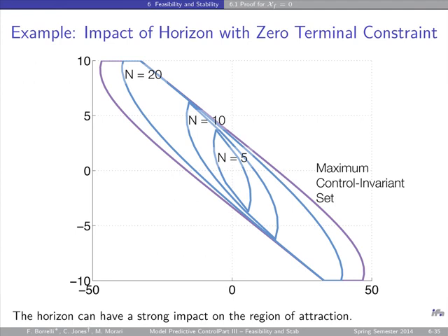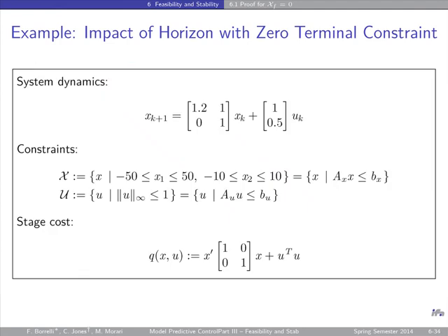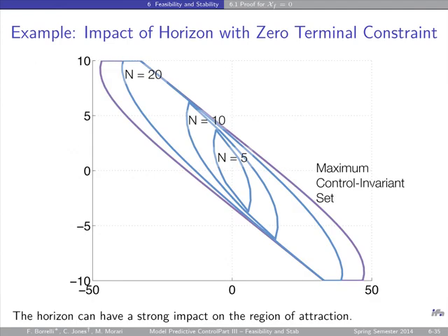how the initial feasible set changes as a function of the horizon. Okay, so the designer here has used the project I just showed, and set up an MPC with xN equals 0. And you see the blue sets here are actually the calligraphic X0, which are equal to O infinity, because of the proof that we have just given. For xN equals 0, you always have persistent feasibility.